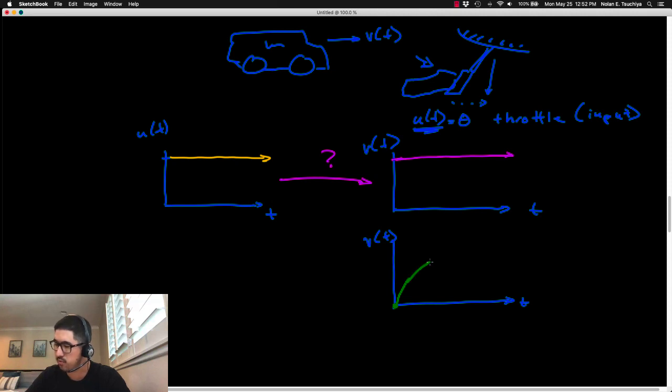Right? If your car is powerful, you accelerate very quickly. And you keep going faster and faster until at some point, assuming you have unlimited road with no stoplights or traffic, eventually something happens. And that something is the amount of aerodynamic drag pushing back on your car is so large that it's equal to the amount of forward thrust provided by your engine. And so you have a net force of 0, so you are no longer accelerating and you reach terminal velocity. Right? So this is basically the fastest that your car can go, and you will remain at that top speed until you release the gas pedal.